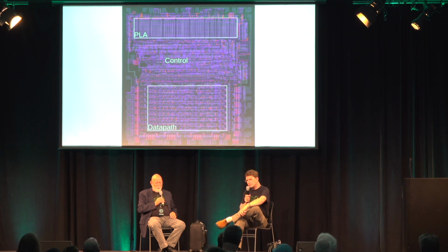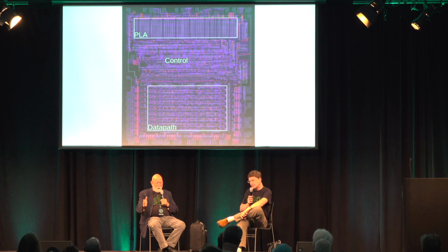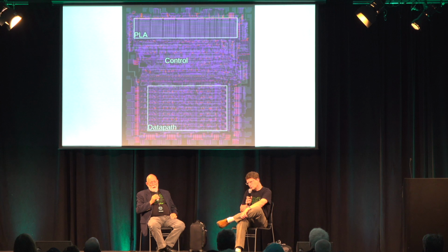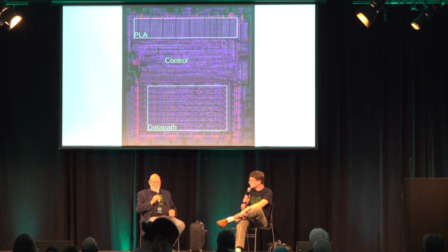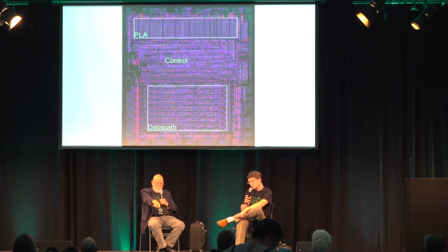Yeah, and so the data bus is on the right, the address low is on the left, the address high is on the bottom, and then the control bus that controls like the clock, the phase 2 clock generators on the top edge, and then you have NMI and IRQ and all these control pins, and you have sync on the left. But anyhow, the idea there is that in order to economize the number of transistors, we brought the opcode in, and then right above where the buffers are there on the right is where we did the pre-decode. So we didn't need a decrementer.